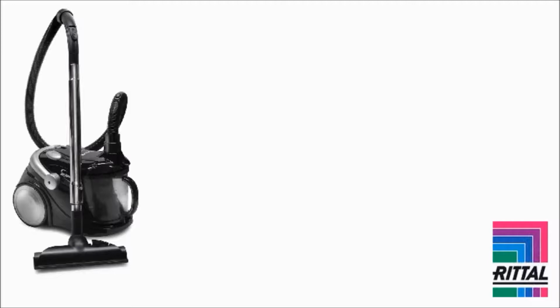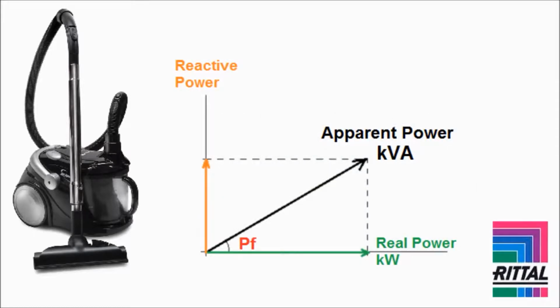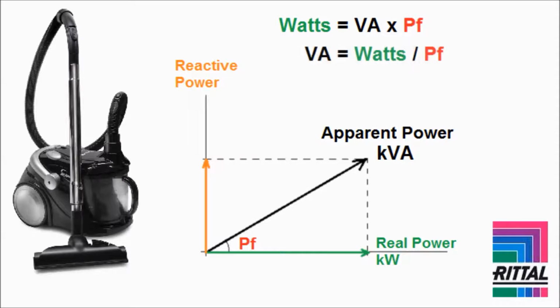Inductive loads, on the other hand, such as a vacuum cleaner or the fans in a server, have a variable power factor, which means that their apparent power draw has both a real and a reactive component. For example, let's take a vacuum cleaner with the following rating: a load of 1.2 kilowatts, and a power factor of 0.8. We can find its kVA rating from the above formula. Since volt-amps multiplied by the power factor equals watts, it follows that volt-amps equals watts divided by the power factor. So, in this case, the volt-amps equals 1200 watts divided by the power factor 0.8, which equals 1.5 kVA.